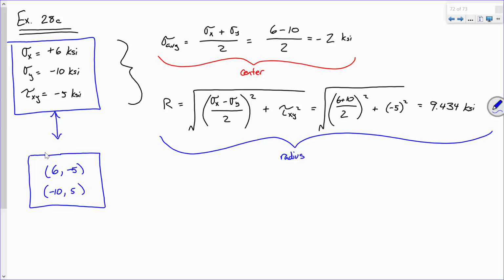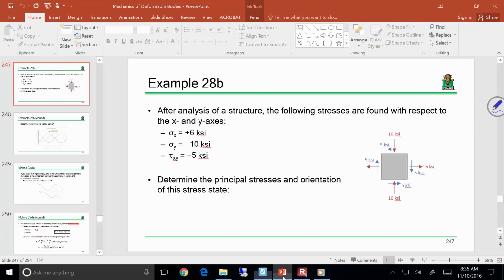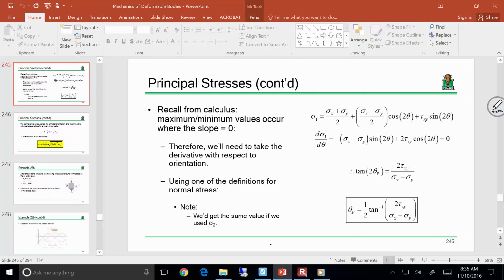Make sense? Any questions? The only reason we double the theta is because we do theta every single time in a formula. That's why, yes. Because when you go through and do the math, you find that your stress rotations, or your new stress state, is really a function of 2 theta and not theta. And that's how Mohr's circle is being developed.